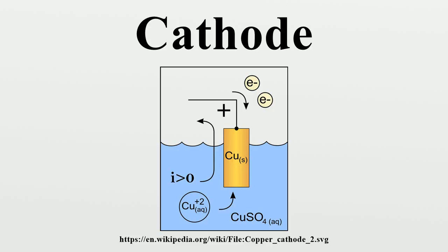Indirectly heated cathode. In this type, the filament is not the cathode but rather heats the cathode, which then emits electrons. Indirectly heated cathodes are used in most devices today. For example, in most vacuum tubes the cathode is a nickel tube with the filament inside it, and the heat from the filament causes the outside surface of the tube to emit electrons. The filament of an indirectly heated cathode is usually called the heater.